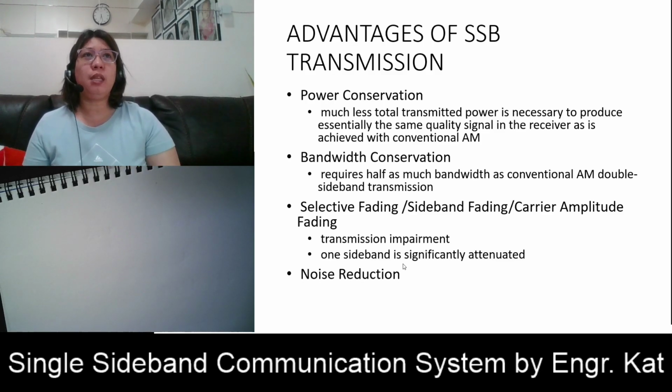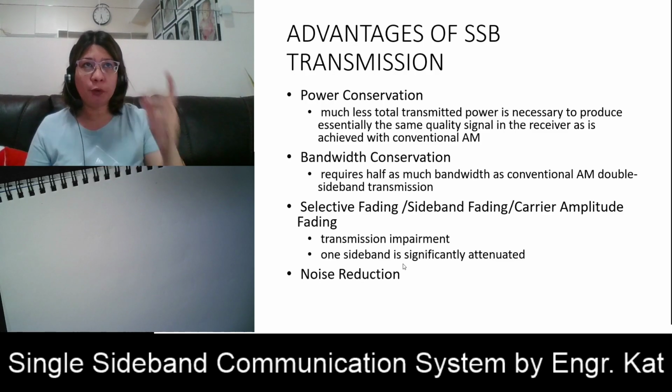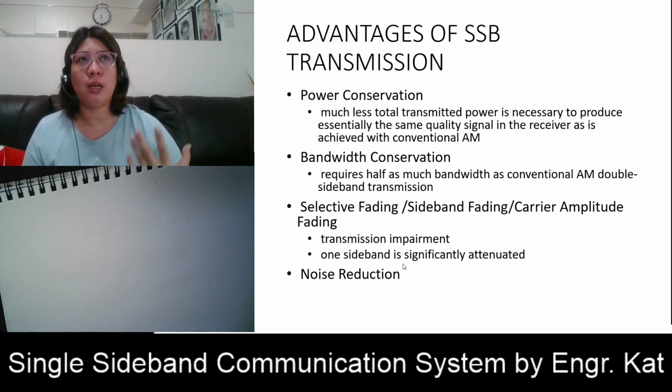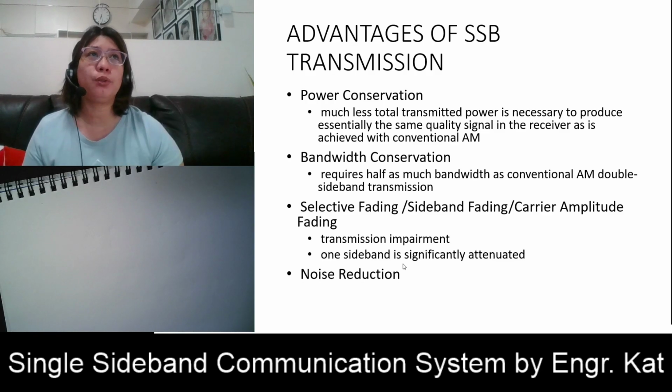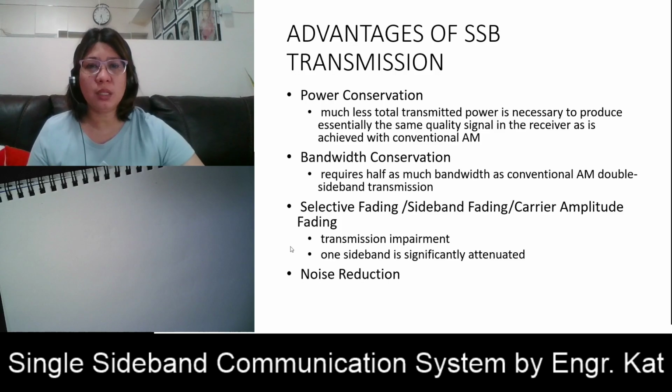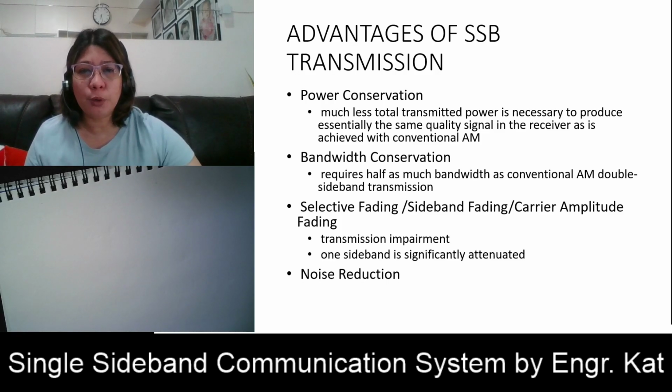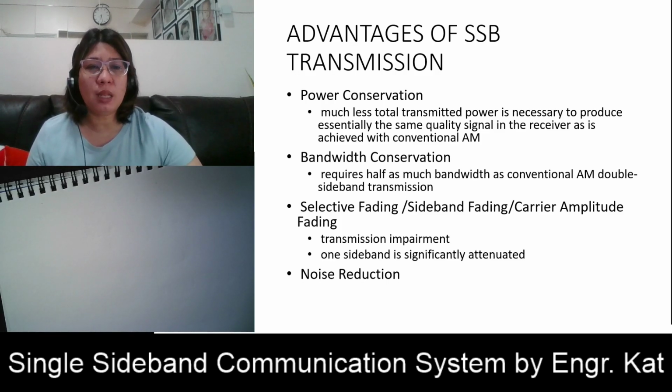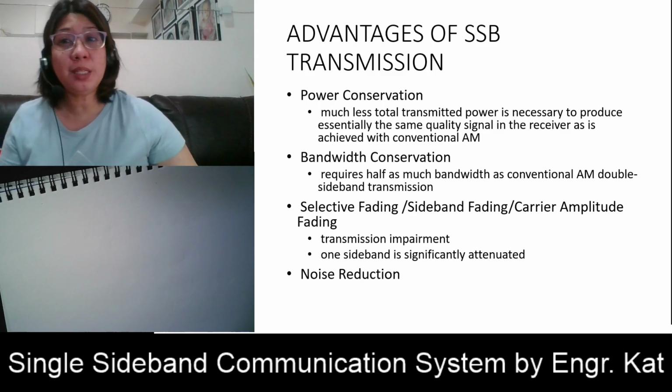Okay, and finally, noise reduction. Of course, half your bandwidth is reduced, also half of your thermal noise power. So these are the four predominant advantages of your single sideband compared with double sideband or conventional AM. Okay, however, there are also disadvantages.